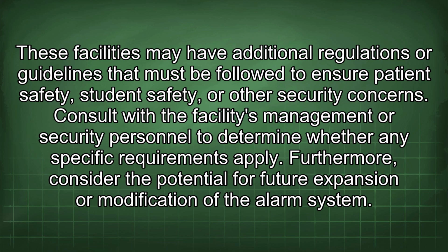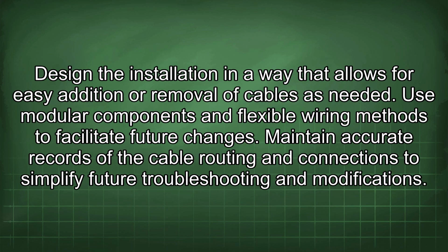Furthermore, consider the potential for future expansion or modification of the alarm system. Design the installation in a way that allows for easy addition or removal of cables as needed. Use modular components and flexible wiring methods to facilitate future changes. Maintain accurate records of the cable routing and connections to simplify future troubleshooting and modifications.